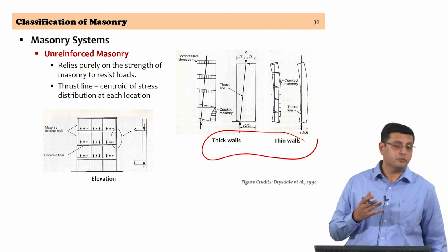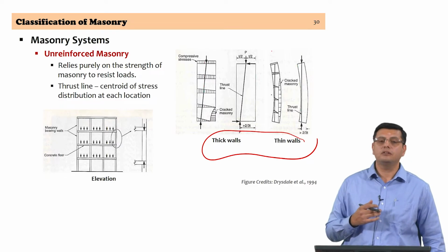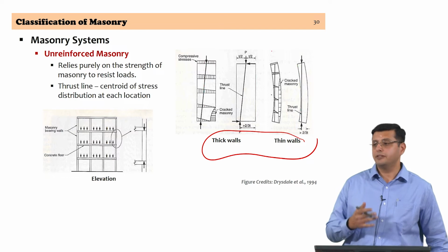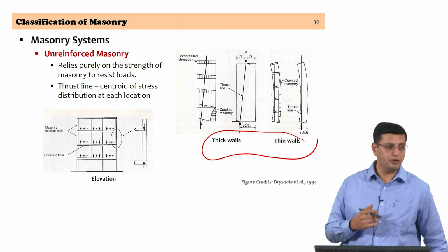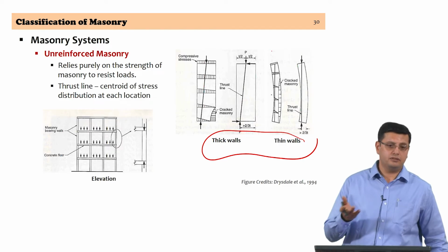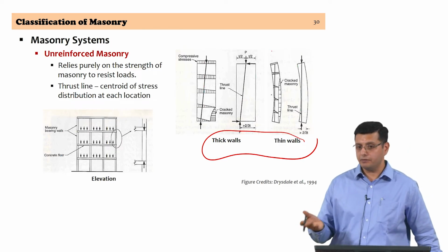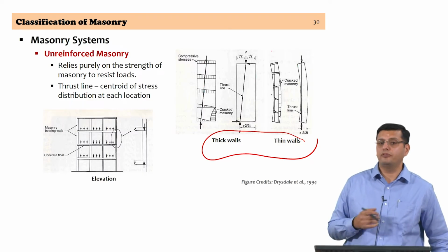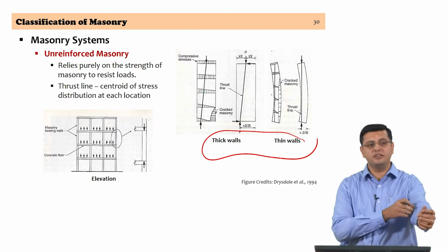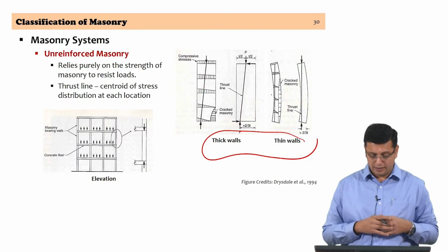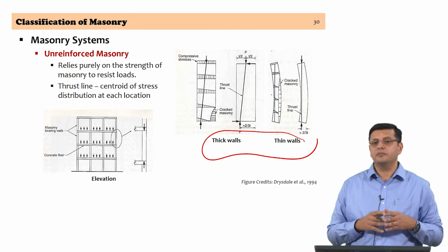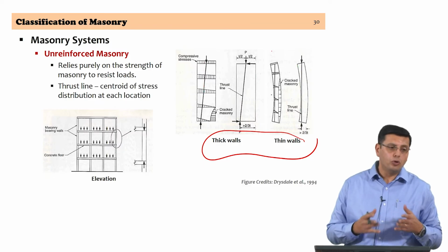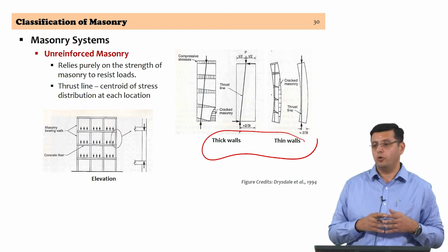Countries such as New Zealand, for example, introduced legislation that required that no new constructions be executed with unreinforced masonry, because when your land is highly seismic, you cannot have a construction that has extremely poor performance if it does not have positive features like good connections between walls that we have discussed earlier. So, unreinforced masonry is predominant today mostly in regions where seismicity is low.